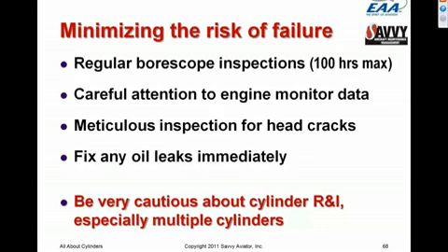Engine monitor data. More and more of our aircraft are equipped with engine monitors, but most owners aren't trained how to interpret it, and most of the engine monitor data just winds up going into the bit bucket with nobody looking at it. I do have a whole webinar on the subject of engine monitors and engine monitor data interpretation, and that's something you might want to take a look at. We need to inspect very, very carefully for head cracks, particularly if the cylinder head has relatively high time on it.